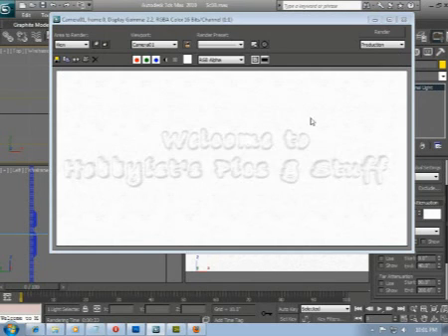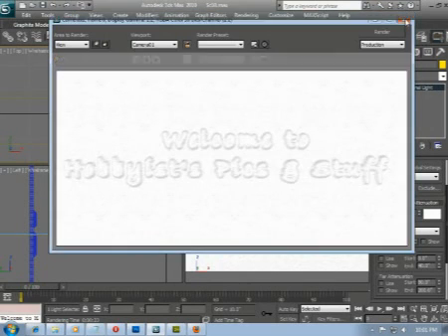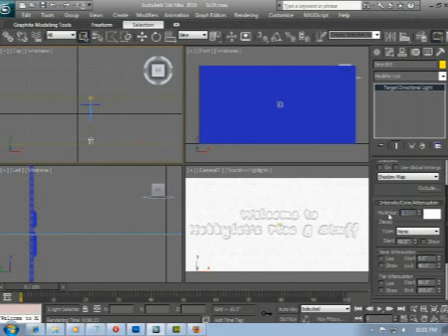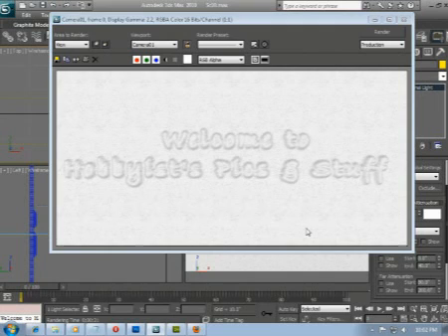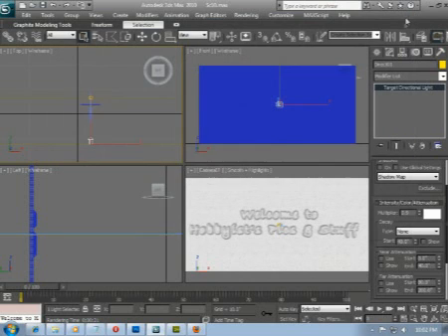okay, that's definitely too high. So close the render window. Let's take the multiplier down to 0.9. Our text in the camera viewport is definitely looking a bit too dark. Let's render again. So rendering and render. Yep, no surprise there. Okay, looks like we may have things set up so that value wound up needing to be just about exactly 1.0. So let's close the render window and set 1.0.